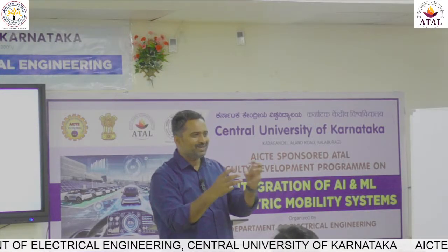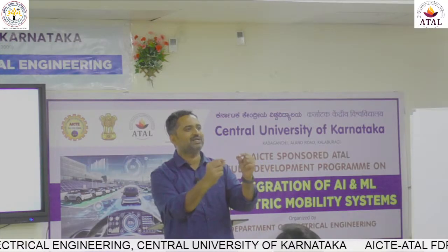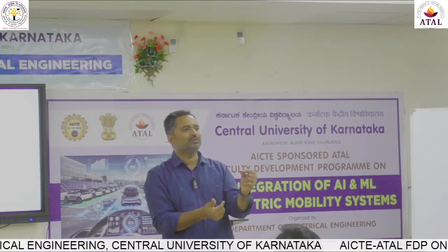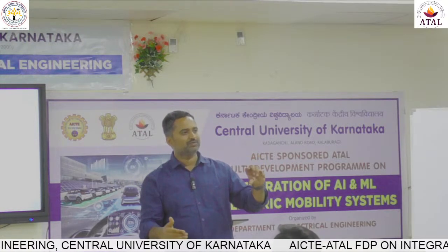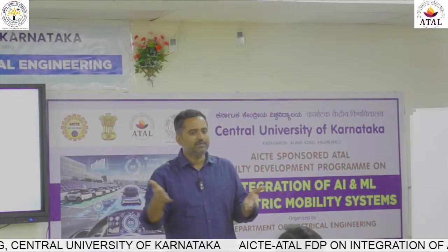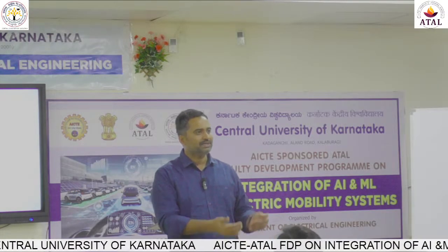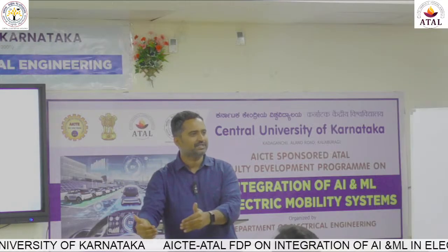You understand, it is not like it was going on continuously. This is the ambiguity we have to bring in, because out of 10 hours if I drive, only 1 hour am I using 12 pole, because 90% of the time you will be in the 5th gear. 5th gear means 4 pole only. At that time flux density is anyhow very low, and hot spots occur only for a very short time; even if they occur, you have to come back.